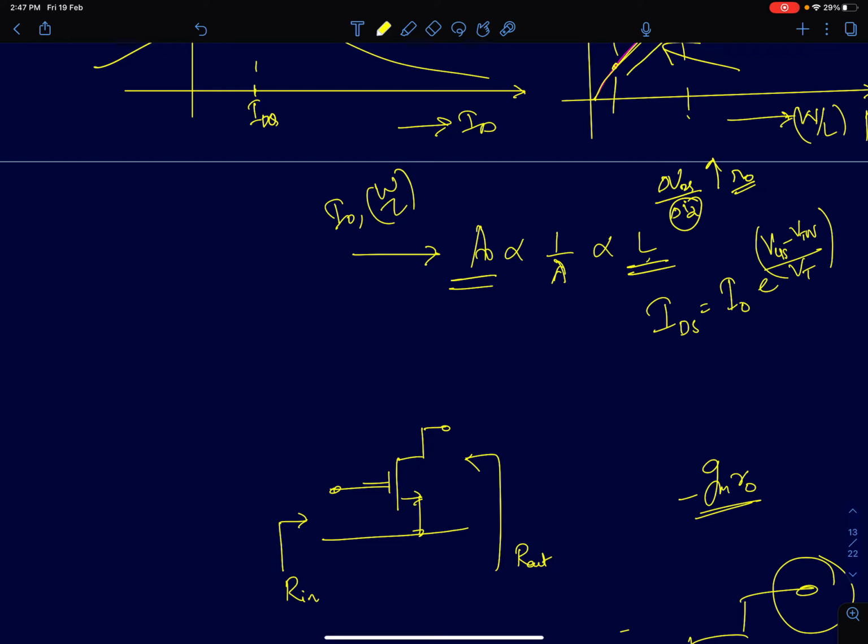As you increase the device length, of course the area of the device increases, because you have to keep your W by L ratio constant to maintain the overdrive voltages to be the same and all of that. So the area of the device increases. The more serious problem is the reduction in the device bandwidth, the maximum speed at which the device can operate. We will talk about that in more detail when we go to the frequency response of MOS amplifiers.